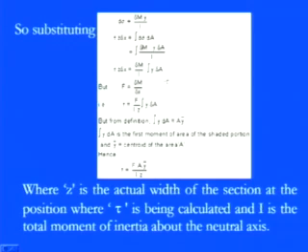Or you just go to the main relation between the shear force and the bending moment, where we have the shear force F equals dM by dx. So with that we can simply put those things here. By keeping this F equals dM by dx, we end up with τ equal to F, the shear force, divided by I into z, because the δM and δx will be giving you the F, times the integration of y into dA.